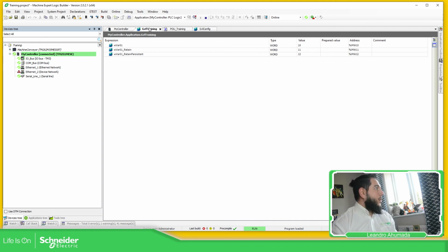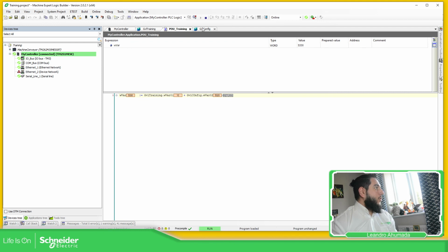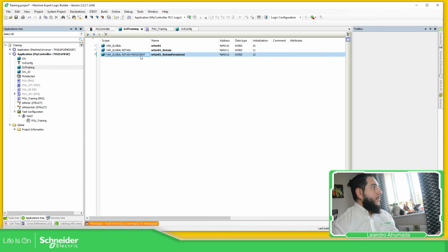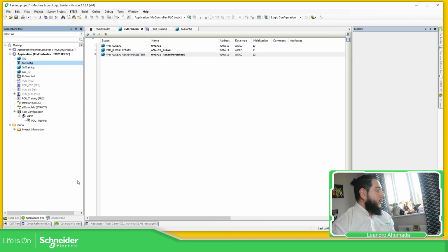Okay, as you saw over here. I just want to check something here. GBL 12. Yes, so if you want to store the information, basically what you can do is to define on the variables global retain persistent. Okay, and then you have that on the GBL. If you define retain persistent and you don't add the GBL with the name, this one, on the configuration, you will receive a message on the system telling you that you haven't added the old instance path in there.